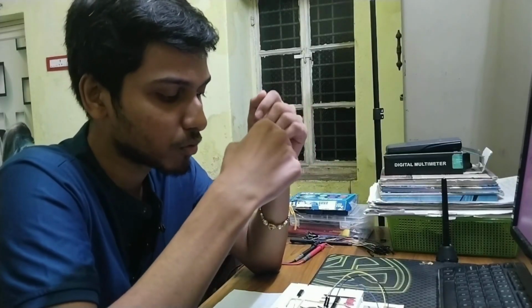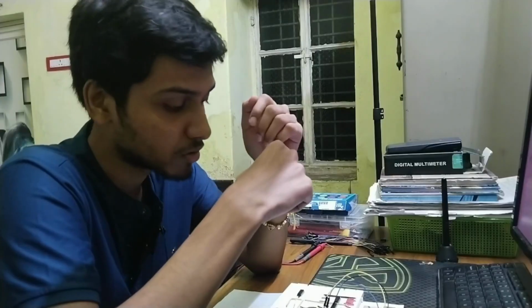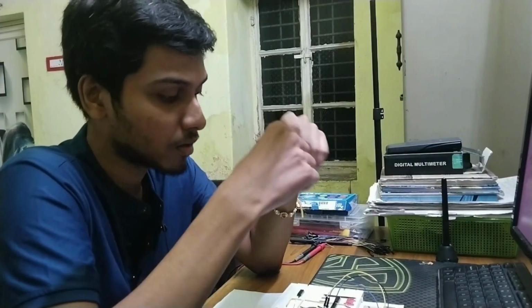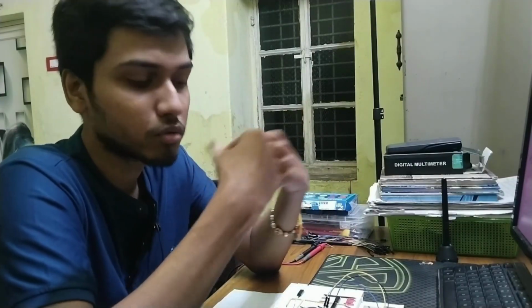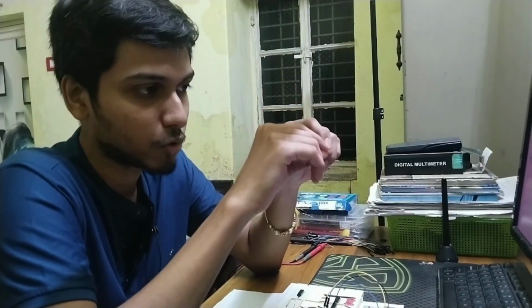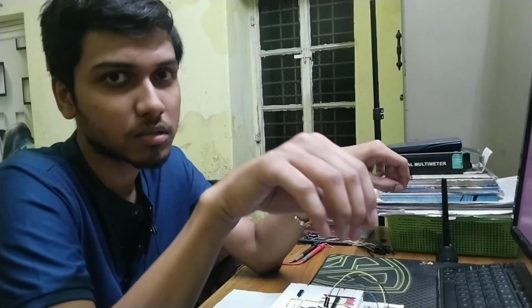Now in our case we are not going to do this manually. That is, we are not going to apply the potential difference across our diodes, then measure the current running through the diode and write it down. We are not going to do it. Instead we are going to use a software and a device which will do it for us. So the software is going to generate different amounts of voltages across our diode, and then it is going to measure the current corresponding to those voltages, and it will plot the potential differences applied on the x-axis, and then it will plot the current running through the devices on the y-axis. In effect, it will generate a graphical representation of the IV characteristics automatically.